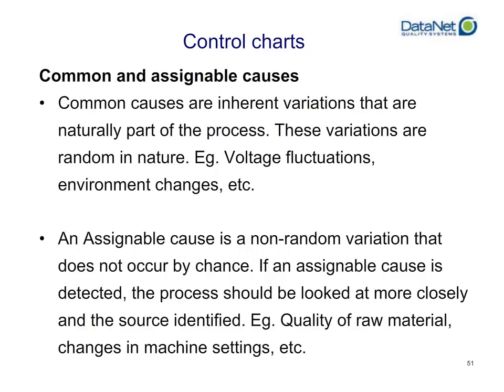Another one could be changes in machine settings. You were running really close to your lower spec limit, and then all of a sudden somebody hits a knob and now it's set to something higher, or maybe somebody thought they were running a different process with the wrong specs and you have an actual shift in your process. That's something that shouldn't occur randomly. That indicates something has acted upon it, not randomly, that can be investigated and hopefully fixed before you've produced any waste.